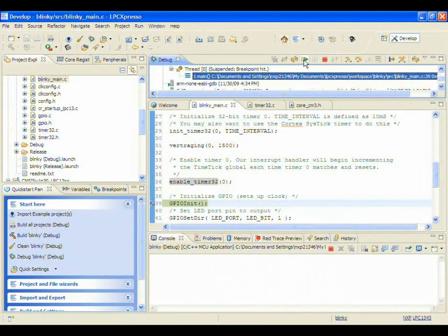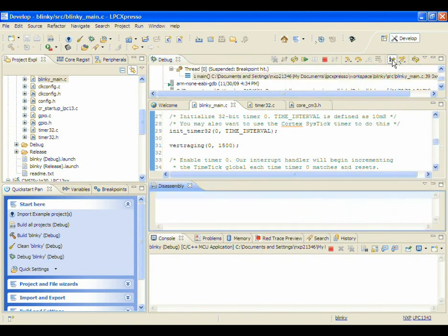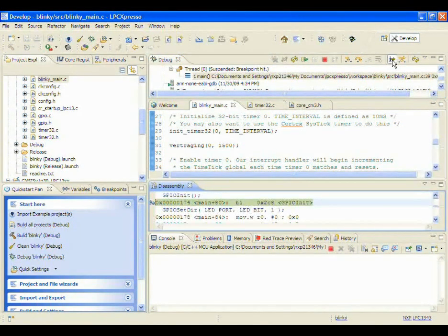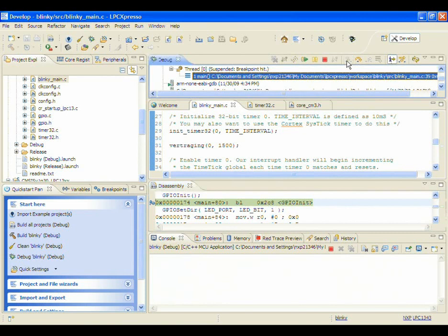Sometimes you track a bug down to a specific line of C code, but you can't figure out what on that line is triggering it. In these cases, you might need to zoom in further. Click the Instruction Execution Mode Debug Toolbar button. This will open a new view that displays disassembly near the current program counter location. It will change the debugger step mode to step individual assembly instructions instead of full C lines. Sometimes this is just what you need to get to the bottom of things.